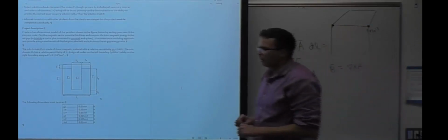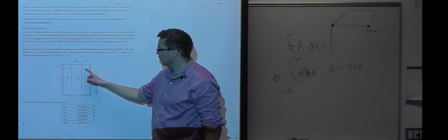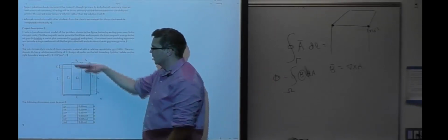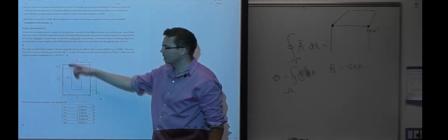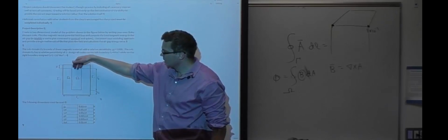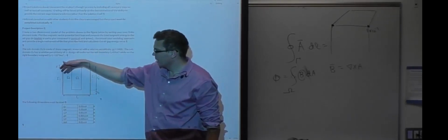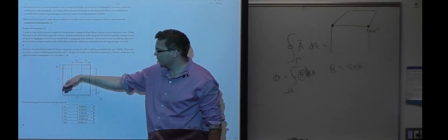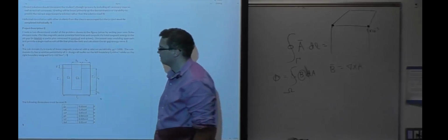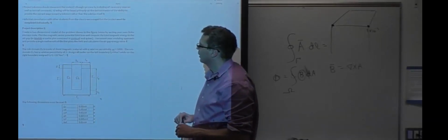Now what happens though is that because there's iron in these, a magnetic material in region 1, the magnetic field will become distorted. It won't want to go from the top down through the air region. It will want to distort and go through the sides, because that has a higher relative permeability. And so your plot should show that.